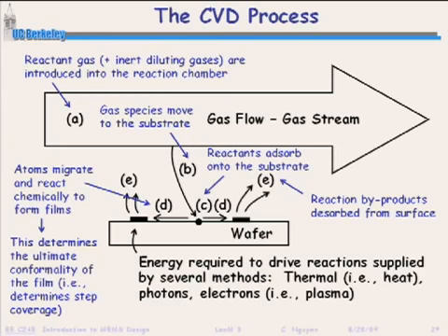So right here I'm going to tell you something you need to remember: the higher the temperature of the CVD process, the more conformal that process is going to be. So you can almost make that decision. If I'm going to deposit polysilicon at 600 degrees C, that's going to be conformal. That's a high temperature. If I'm going to deposit oxide at 400 degrees C, nope, that's not high enough. It's not going to be conformal. So you can make that decision almost entirely by what temperature you are depositing at, whether it's going to be conformal or not. That's a very important thing that I just said.